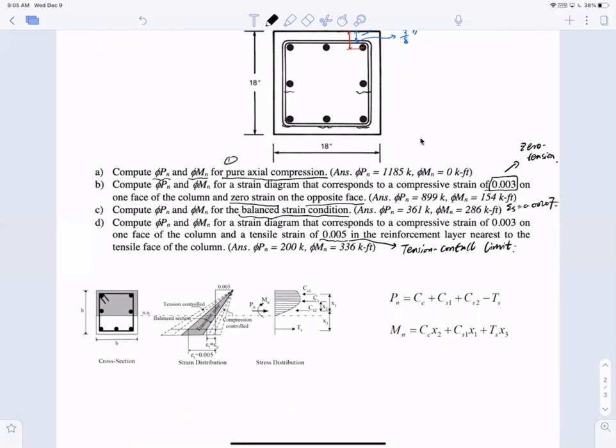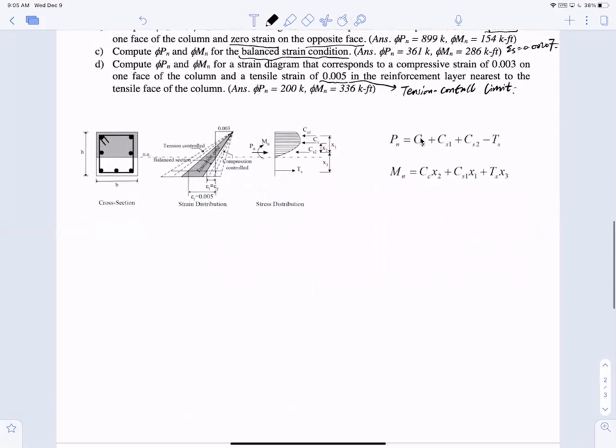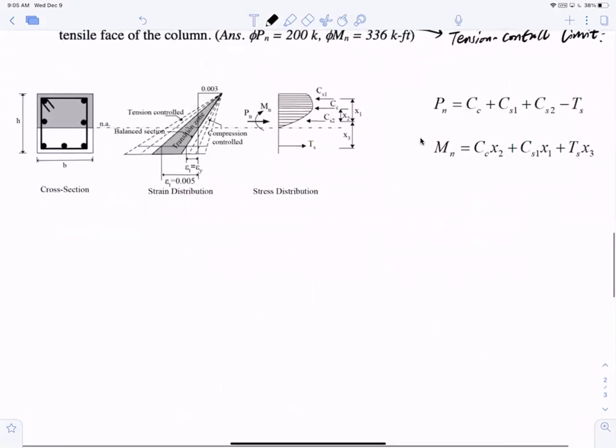So this is clear. Why I want to put this problem out is because in the previous lecture, we did not cover the example with another layer of reinforcement in the middle. The difference is actually not much. If we draw the strain diagram, and just take this picture from the notes, you can see that if I have center layer bars, on top of what we talked about before, I have compression from the concrete, compression from the first layer reinforcement, if I call it 1, and I also have a compression from the second layer reinforcement.